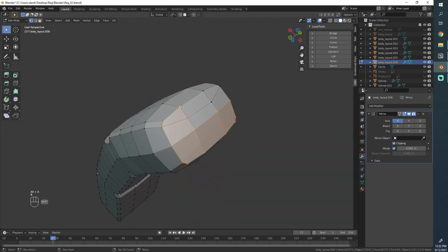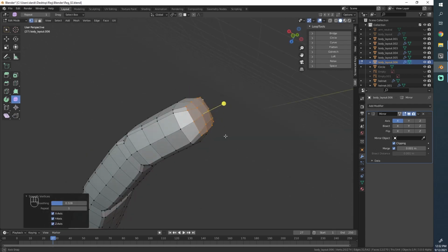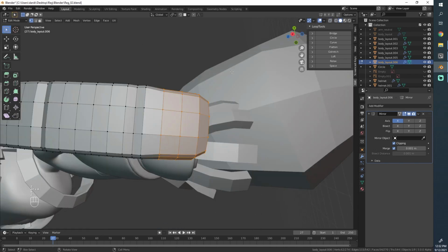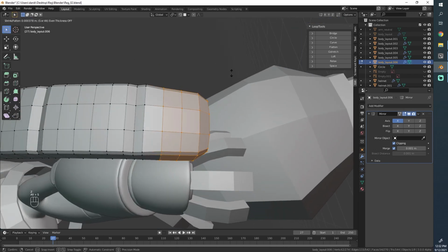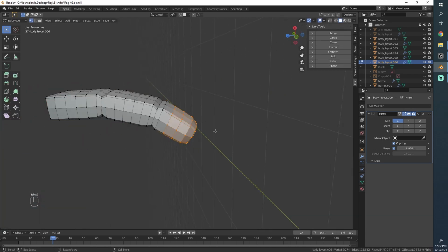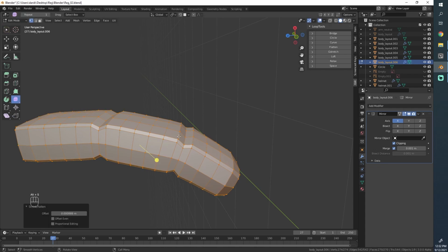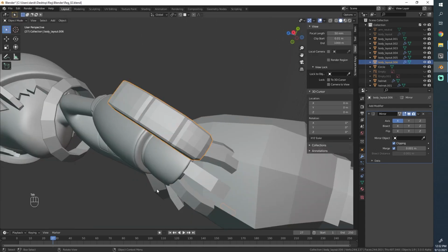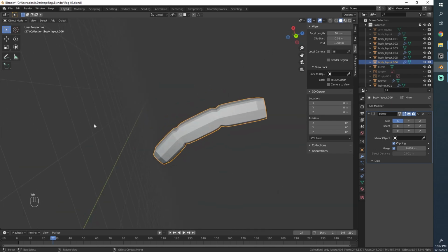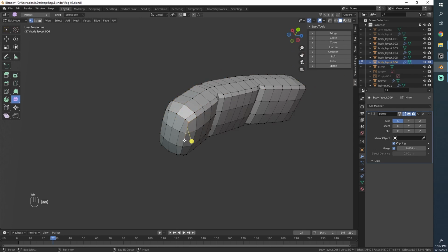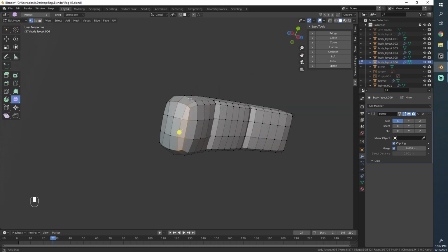So let's select the entire front here one more time. Select the smooth tool and just drag out a little bit here. Smooth it out. Finally, I think we lost a little bit of volume here, so I'm selecting the entire tip and Alt S to inflate a little bit. And one more time, select the entire thing, maybe inflate it a little bit, maybe smooth it a little bit. At this point I'm just trying to get it a bit more organic. That looks nice. We can do some additional details in sculpting later, but that's a very nice space to get started with.